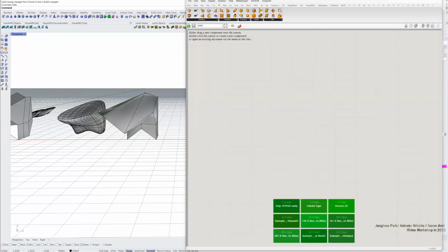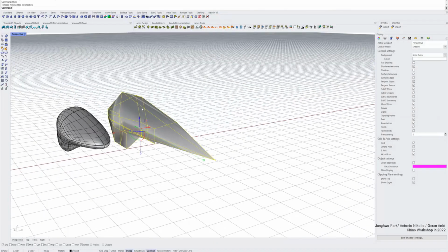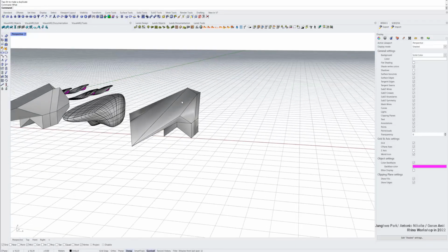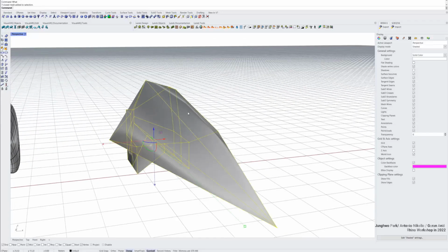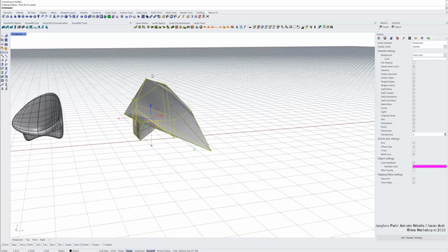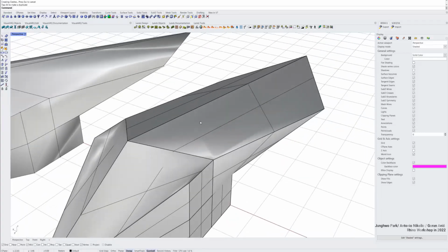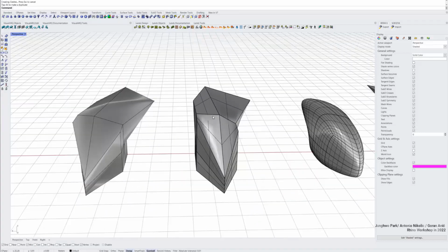Ignore this Grasshopper part. Once you have that mesh, then we know that this is mesh. This mesh element now we can convert to NURBS. If you convert to NURBS, there are some mesh options, and you can say different trim, triangular, and so on. You can change, and when I convert, this is now the NURBS surface of that particular geometry.